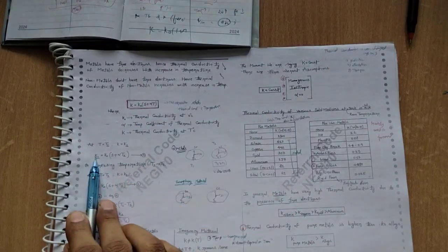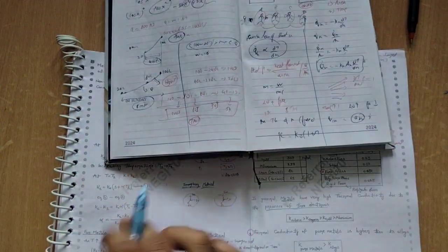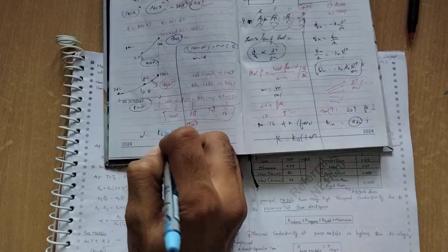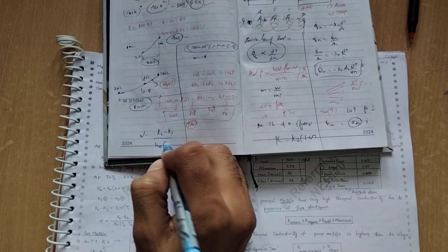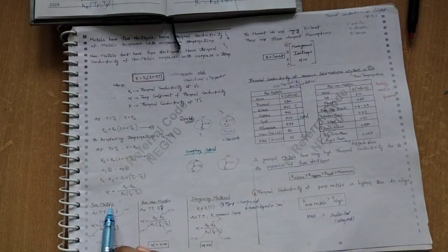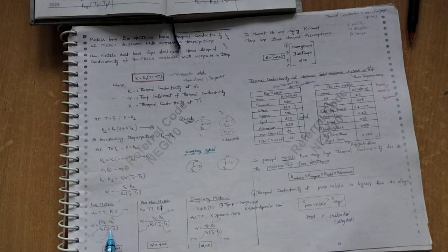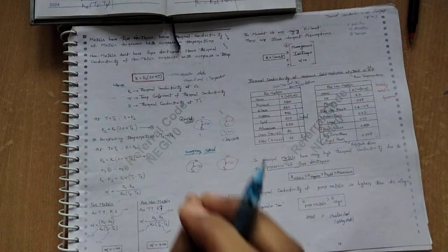So you can see K1 and K2. We compare K1 and K2 with respect to alpha. So what is alpha when we compare two materials? Alpha is (K2 minus K1) divided by K naught times (T2 minus T1). For metals, as temperature increases the thermal conductivity decreases. Everything else is positive, but K decreases, so alpha tends to be negative; it is a decreasing state.